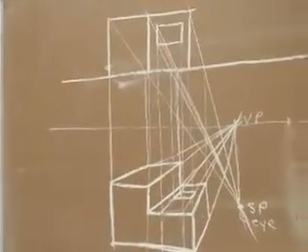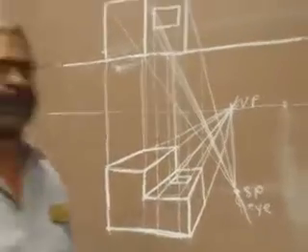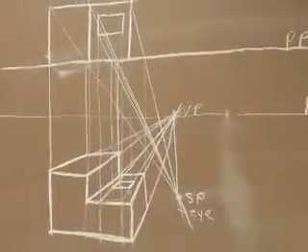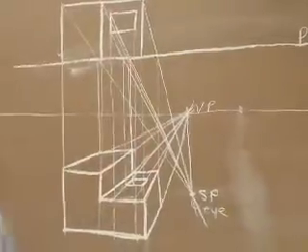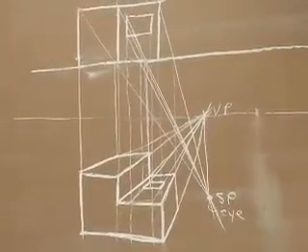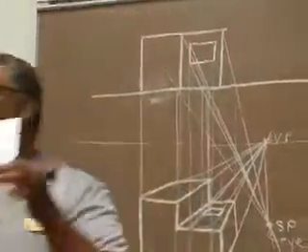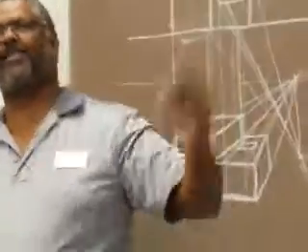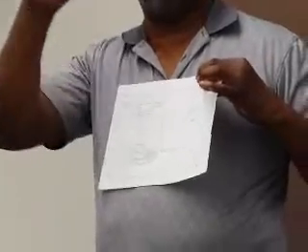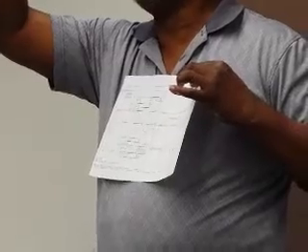All right, now what do you do when you're starting with a blank sheet of paper? You take the measurements that I have given you. Now on this sheet here, if you notice, the measurements are coming from the edge of your paper. So you take that 11 by 17 sheet of paper and measure from the edges of the paper, not the title block. And when you get done, it should be sitting on there.